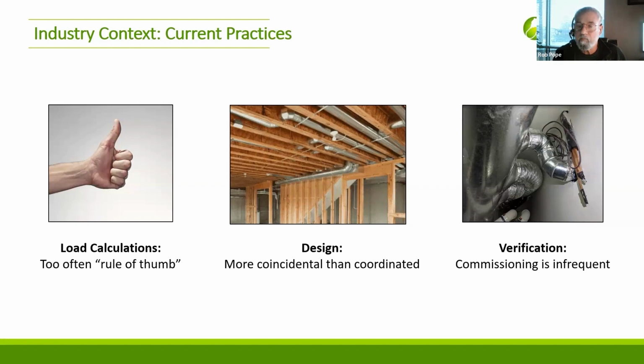And then finally, commissioning. If you've done your load calculations and you've done a great design, now you've got to execute it. And the only way to know that it was executed well enough to meet the design intent, of course, is to check it. And unfortunately, that doesn't happen often enough. That's the verification part, making sure that the system itself in general, and all the subsystems within it, are all working properly, all configured right and customized for the application it's in.